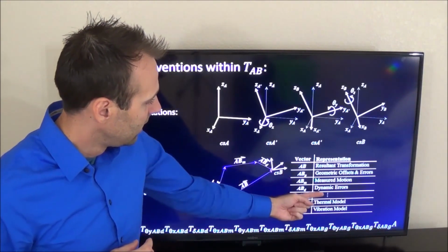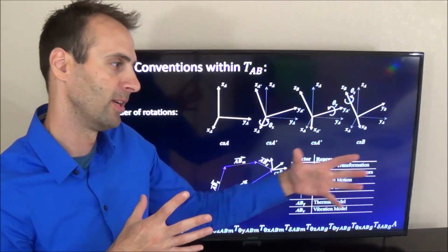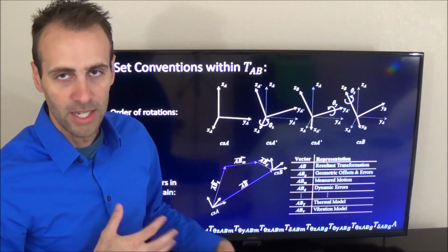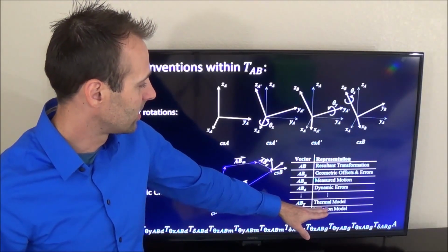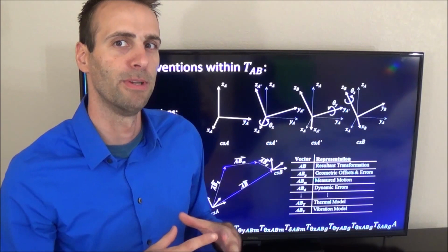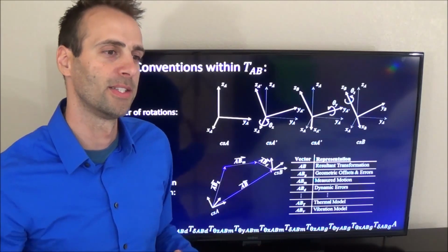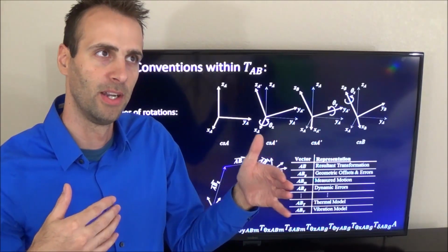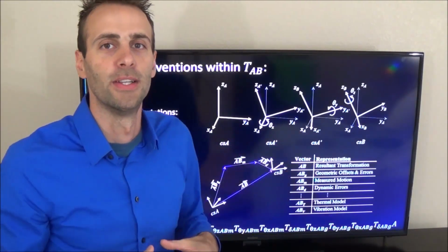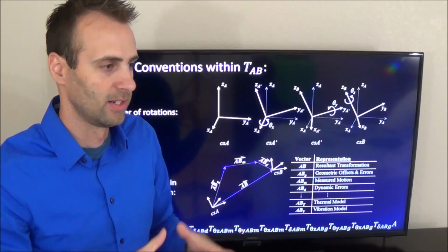And then I do dynamic vector or dynamic errors, which again would be like a function of how much I moved. So like that would be like your meandering and things like that. And there could be as many of these as you want. So for example, I would put the thermal model somewhere near the end, right? To say like, well, if my machine has been on this long or I've been working it this much, that gets added in. And then vibration, right? So it's like, well, if I came to that position with this velocity and with this acceleration, I'm going to add this error in there. And that's how, like in the last video, the Zeiss CMM sort of deals with that wet noodles.